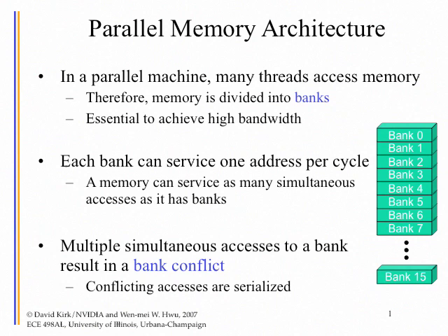Now, this is called bank conflict. Bank conflicts in these kinds of memory systems are usually handled by stalling the processors. Essentially, the 8 processors all simultaneously generate one address each, and all send the address over. There's a hardware mechanism that looks at parts of the address and figures out very quickly.